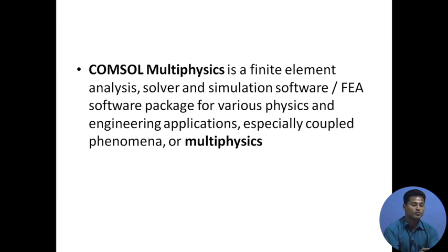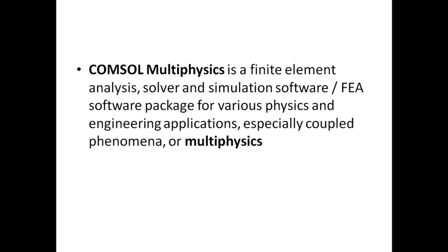Before starting COMSOL Multiphysics, I want to say some words about it. It is newly emerged in the market. It is a finite element analysis solver, and the strong point of the finite element solver is that it divides the entire geometry into different small elements, and it integrates the governing partial differential equation over those elements after being multiplied by a weighted function. Generally, the Galerkin method of weighted residual is used.